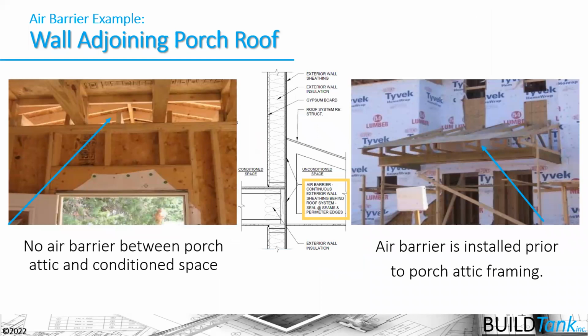So these are just two quick examples of where the air barrier has not been continuously applied. And in this case, it's at this porch roof connection, which brings up the notion that about 90% of the air barrier details are actually the framer's responsibility. They need to get the continuity of the sheathing, and in this case, the weather-resistant barrier behind the trusses that frame out this front porch area before the trusses are installed here. So it's a sequencing issue.